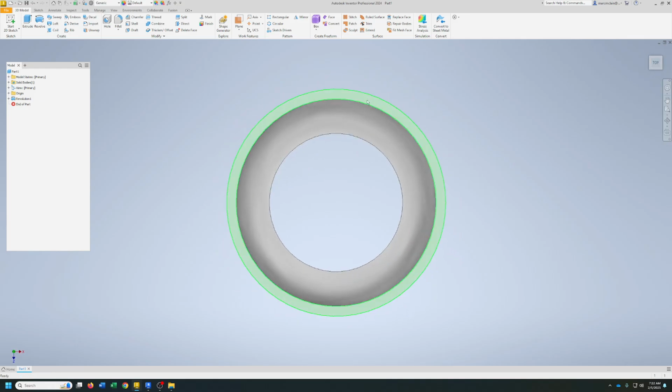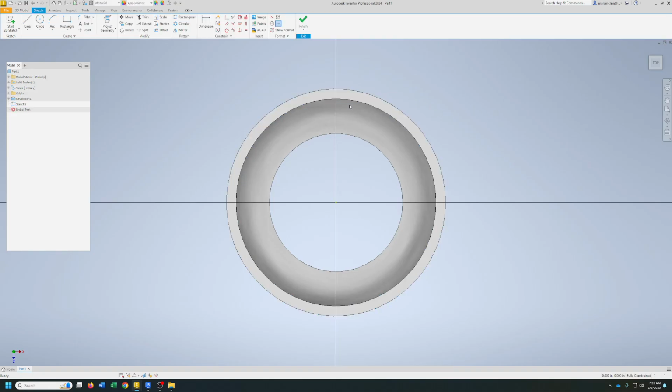Let's go up to the top and pick the top edge. New sketch. Alright, so we got 4 of these little deals. So I'm just going to put the circle here somewhere. And this is going to be a radius of 0.5. Now I'm going to do a circle. And it's going to be a diameter of 4.25. So I'm just going to put it about right there. There we go. That needs to be right on that corner.